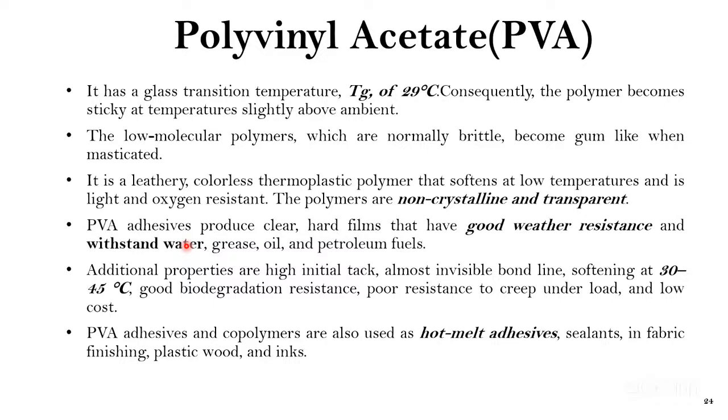If some water falls on it, it is still quite resistant. With some glues, when they come in contact with water, the adhesive comes out of the attachment. In that case, PVA has better resistance to water as well as grease, oil, or petroleum fuel.